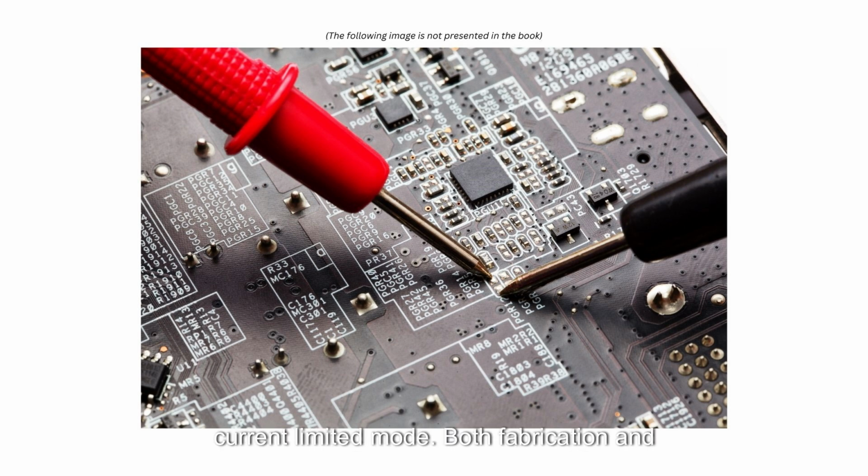Both fabrication and assembly operations may perform continuity tests to ensure the quality of their service. In fabrication, continuity tests are performed on the bare board, PWB, for opens and shorts between signals. This requires a netlist to know the connectivity that is supposed to exist between the pins of each component. These are also referred to as lands.